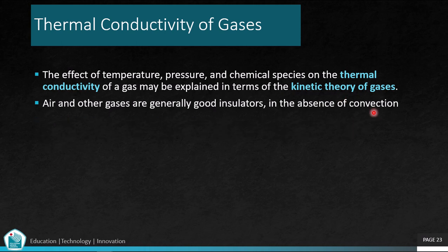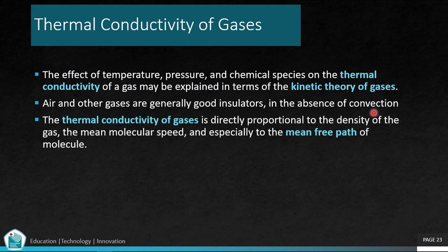Therefore, many insulating materials, for example polyester, function simply by having a large number of gas-filled pockets which prevent large-scale convection. Alternation of gas pockets and solid material means the heat must be transferred through many interfaces, causing a rapid decrease in heat transfer.